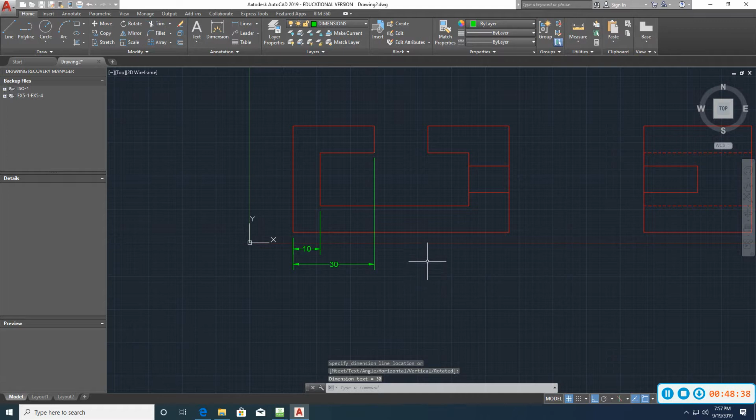The way I'm dimensioning this right now is because, you know, I'm not a machinist, but I've worked with machines in the past in my life, and they like for you to pick one datum point and reference all your dimensions from that one datum point. So you just keep clicking here. This is the next intersection, right?